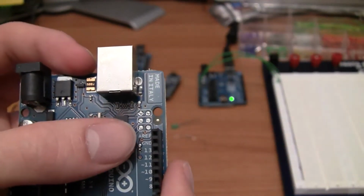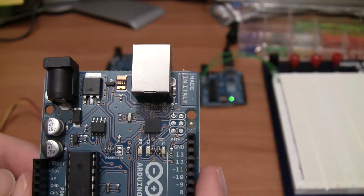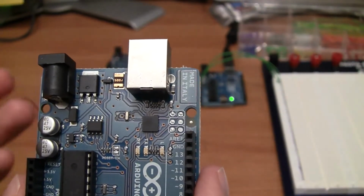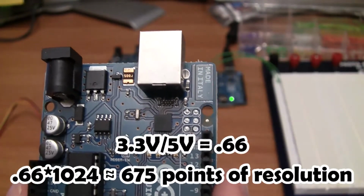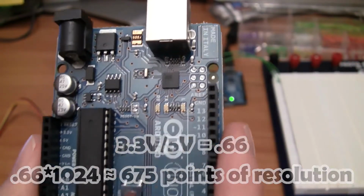Here we can see the analog reference pin that I was talking about. You might want to consider using an external analog reference if you're only using sensors that go from 0 to 3.3 volts on a 5 volt Arduino. The reason for this is that the values from 3.3 volts up to 5 volts, if you use the default 5 volt reference, will basically be excluded and you'll be getting less resolution than you potentially could. Using an external voltage reference allows you to eliminate that problem.